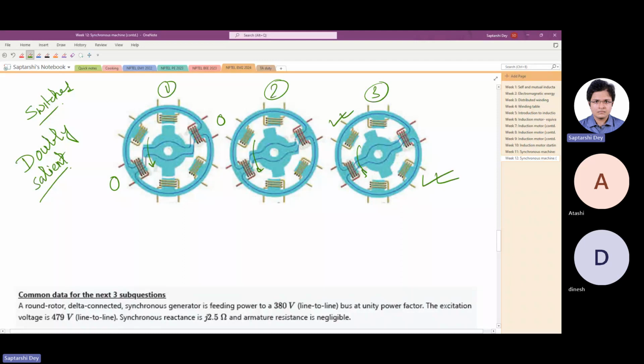So now you can understand one thing here, that you cannot simply keep on firing the phases. You have to know the position of the rotor, the angular position of the rotor. Based on that only you can turn on the phases. That means there needs to be something that would control the turn on and turn off of the phases based on the rotor position, right?